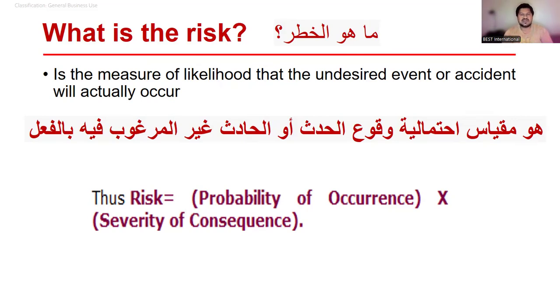Then severity. What is the severity? Consequences would be terrible because all three zones are critically very dangerous. If we're talking about zone 0 or zone 20, they are more dangerous, right? A rapid explosion, a rapid fire incident could happen. So all things within that area, including the employees, we call them affected employees, could be in danger, and a fatal incident could happen. So consequences, of course, in the shape of human life as well as asset damage or destruction. We can give 5 for that as well. So 5 multiplied by 5 is equal to 25, and our criteria is 20 to 25.